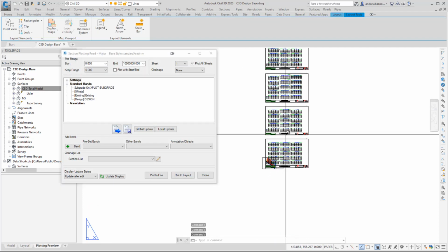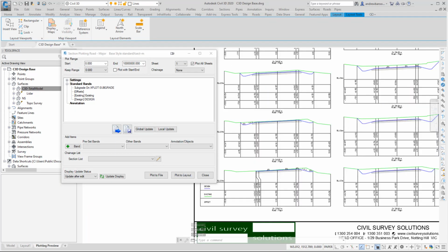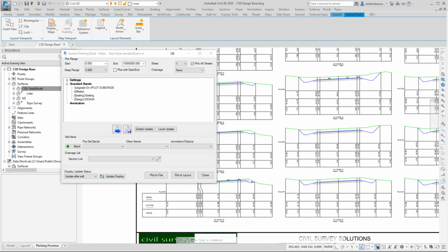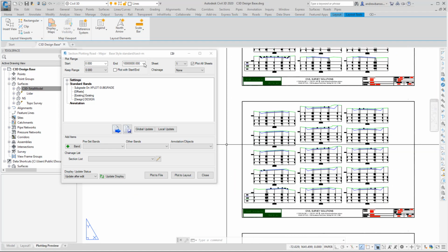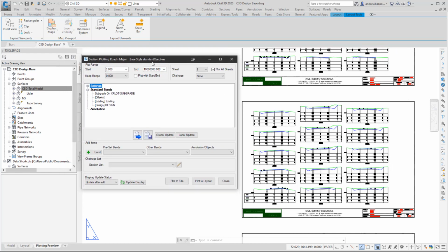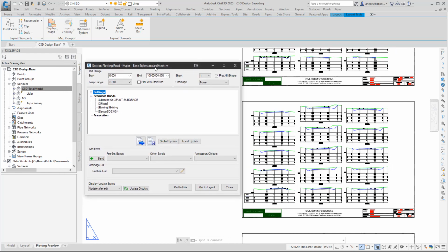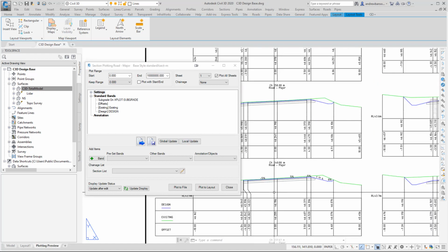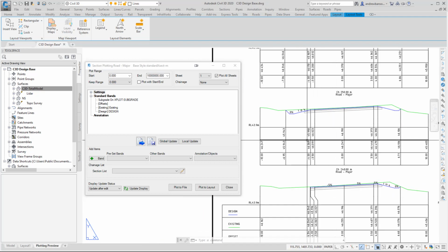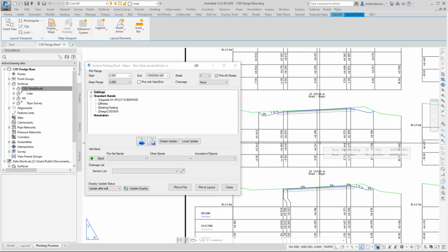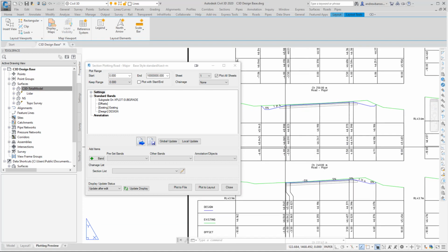So when I do that, we enter preview mode, where I can see a preview of all of the cross sections. Now, also displayed is this cross section options window, and this is where we can customize the plot. I'm not going to go into all the setup here. You can do a lot of things like displaying extra information. Maybe I want to show blocks, boundary, guideposts, that type of thing. Wide range of customization with cross-section plots.